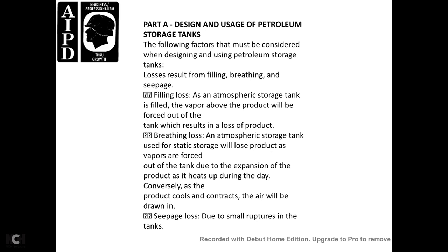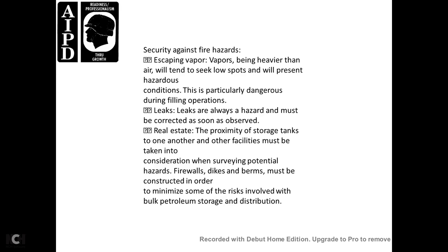Breathing loss: in an atmospheric storage tank used for static storage, there is a loss of product as vapor is forced out of the tank due to the expansion of the product as it heats up during the day. Conversely, as the product cools and contracts, air will be drawn in. Seepage loss is due to small ruptures in the tank.